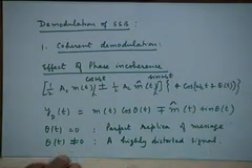So that shows that if I use a coherent demodulator for demodulating SSB signals, such a demodulator will be even more sensitive to frequency and phase offsets than DSB-SC demodulation using the same demodulator. So that's something that you have to keep in mind. Now, fortunately, it is possible to effect this demodulation with better tolerance to phase and frequency offset, which can of course be removed by manual tuning, by another method which we shall discuss next time.